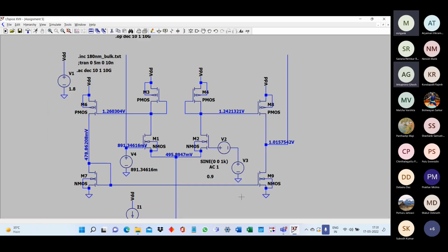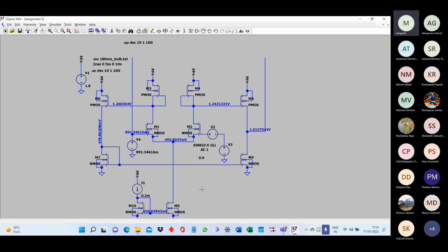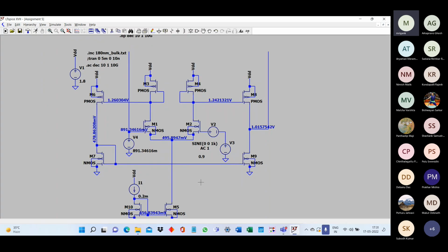Sir, we can, if you change, remember the L, because that will increase our... That is okay, but you remember that there is a relationship between the currents in this case, right? So if you change the DC bias current in one branch, the DC bias of the other branches will get affected immediately.